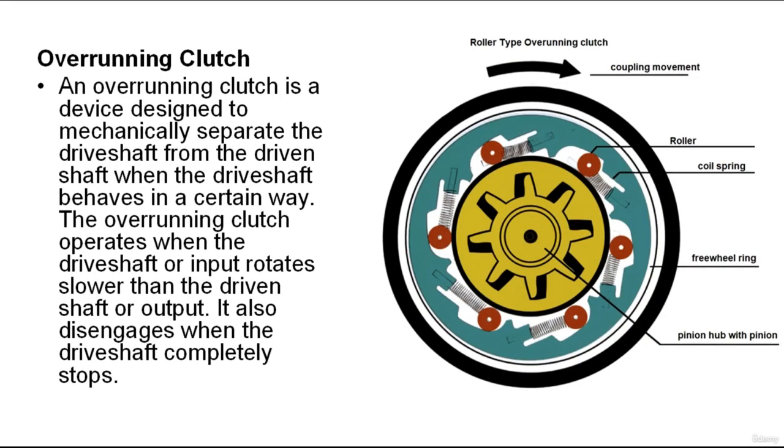Overrunning clutch. An overrunning clutch keeps the stator assembly from rotating when driven in one direction and permits overrunning rotation when turned in the opposite direction. Rotating stators generally use a roller-type overrunning clutch that allows the stator to freewheel when the speed of the turbine and impeller reach the coupling point.